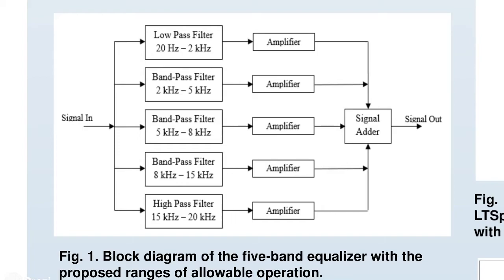For this equalizer, we decided to go with a 5-band equalizer system, comprising 5 different filters and amplifiers to be added by a signal adder on the way out. We chose to do this in 2 separate banks, passive and active. We chose to split these instead of doing them in single circuits so we could better modify our low-pass, band passes, and high-pass filters without modifying our amplifier gain.